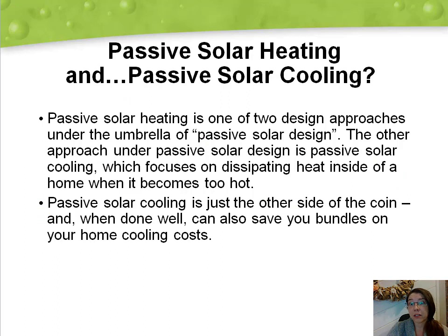All right, passive solar heating and passive solar cooling. So we've been talking about solar heating, but does that mean that it doesn't work for cooling at home? No, that's not the case. Passive solar heating is one of just two design approaches under the umbrella of passive solar design. So that would include heating and cooling. The other approach under passive solar design is passive solar cooling, which focuses on dissipating heat or getting rid of heat inside of the home when it becomes too hot. So that would be more useful for areas that are tropical or much warmer, maybe Arizona or even Florida,